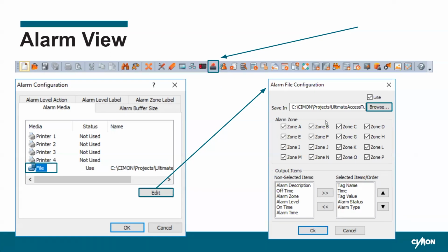Otherwise, the GUI object will store everything for you. Nefarious action meaning maybe someone fell asleep at the wheel, an alarm happened, they woke up, they realized, oh, I shouldn't have fallen asleep, and now an alarm happened, I don't want to get in trouble. They can actually delete the alarm. So you can remove the delete button from the alarm summary, or you can track it historically and it will take into account deleted alarms. They will not be able to find this, I promise you. As long as you can store and tuck this away in a proper place, you will be able to track nefarious action within your project.